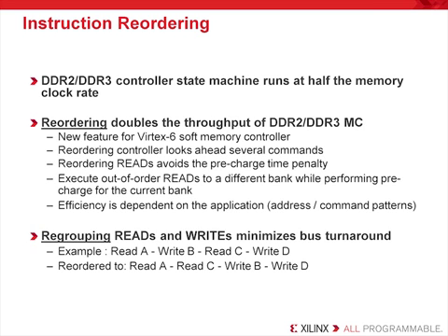This is because if the commands are a string of read-write, the bus turnaround time will introduce a lot of dead states. And if the read or write commands are not accessing existing open rows, the pre-charge time can also add dead states. These dead states, or gaps, in the data bus are a consequence of the way DRAMs operate. To get the maximum bandwidth, the controller needs to minimize the read-write type of accesses and also maximize accesses to the open rows.